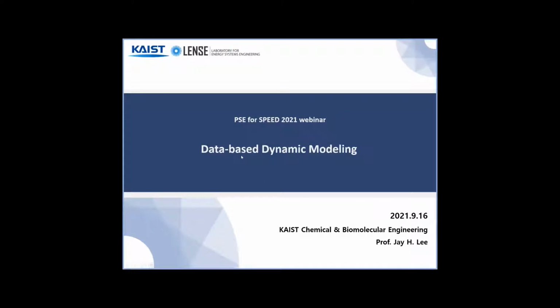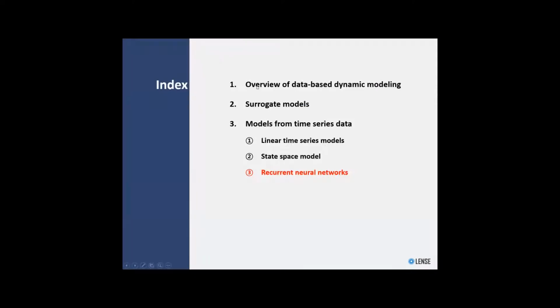I'd like to talk to you about data-driven dynamic modeling. And this is my ambitious agenda for the lecture. I will make a short overview of data-driven dynamic modeling, and then two topics that I want to talk about: surrogate modeling and modeling using time series data. In time series modeling, you can start with linear time series models. Then there's a state space version of it. And then there's the non-linear version of it, which is recurrent neural networks.